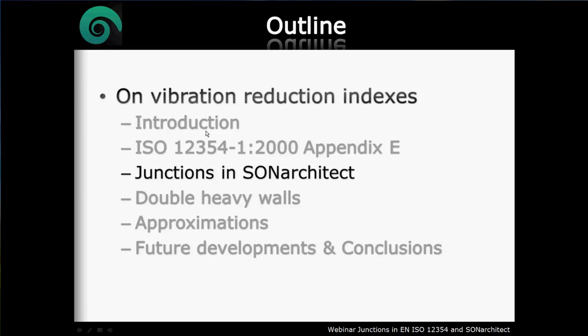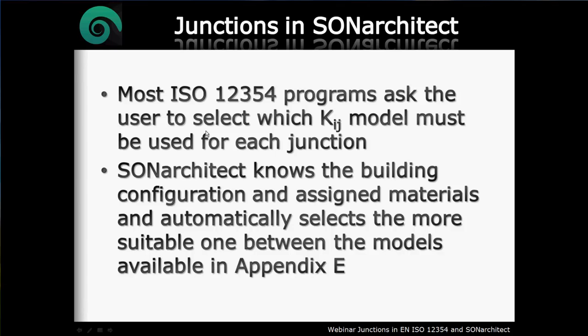Okay, let's see how these models, how these junctions are implemented into SONarchitect. Maybe you are used to other software tools for calculating sound insulation, and in those programs you need to insert the information about which specific model you want to use for a very specific flanking transmission calculation, for the calculation of a given flanking path.